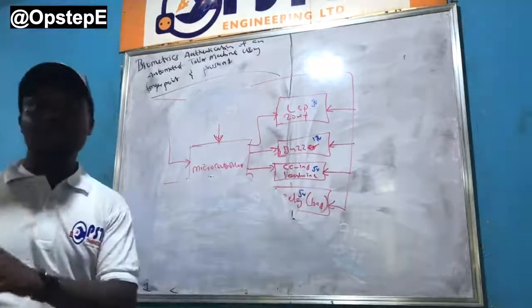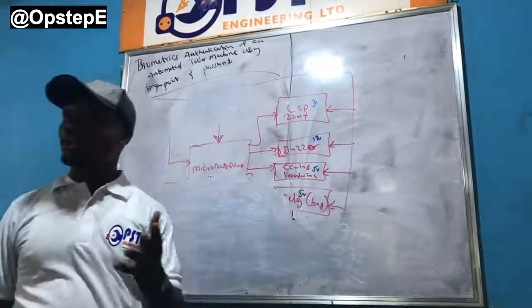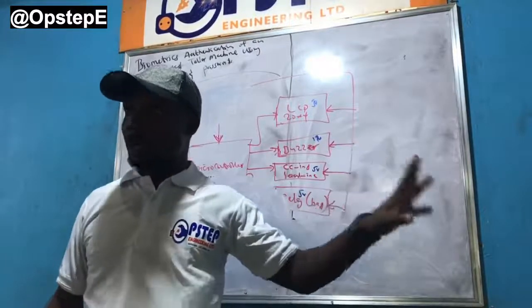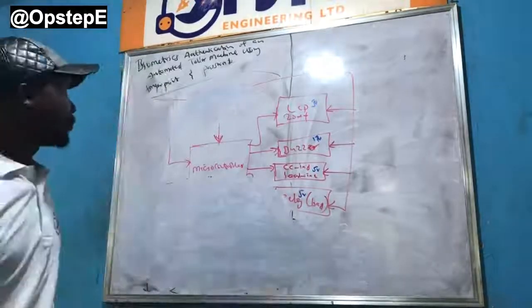But of course, don't forget, if it's 4x4, you need 4 on the column, you need 4 on the row. And that by itself takes a whole port from the microcontroller. Does it make sense? Alright.